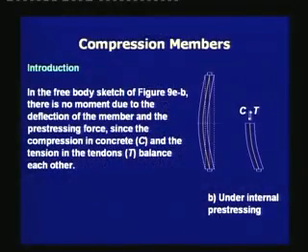In the second case, for a prestressing, in the free body sketch, there is no moment due to the deflection of the member under the prestressing force, since the compression in concrete, which is C, and the tension in the tendons, which is T, balance each other.